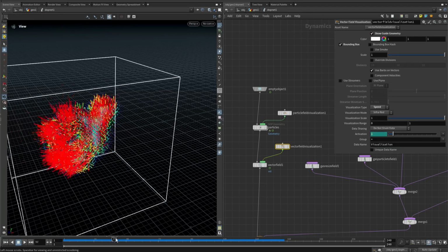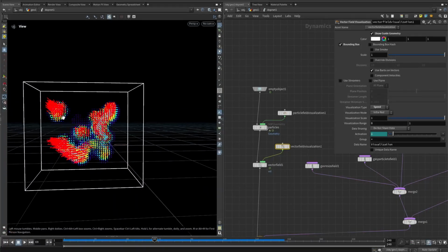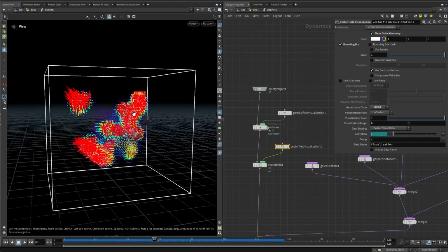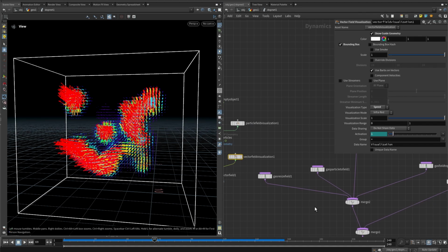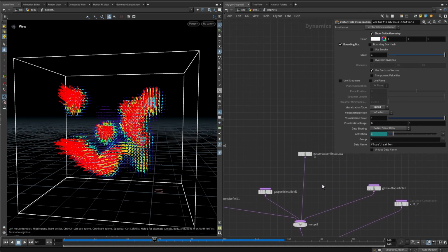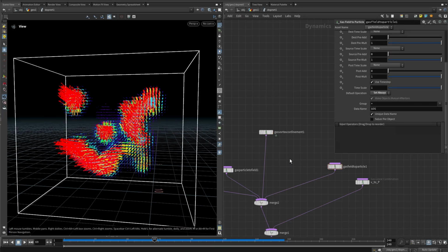and let's play it a bit. And as we said in the previous episode about the divergence and how to get the volume non-divergent, the velocities will spread out around the field around them. This is a core part of any fluid solver, and we need to add that now. So let's add that after the velocities and before converting the velocity field to particles.